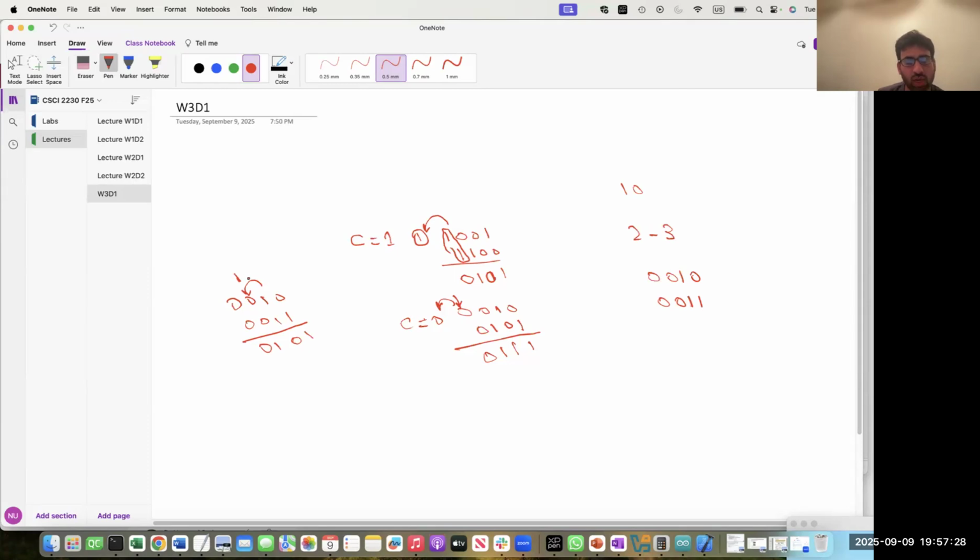So when I have a carry from the half position, or half the size of the register, then your H flag will be set equal to 1. I'm just giving the example using 4-bit, but actually we have 8-bit, which basically means that when there is a carry out from bit position B3 to B4, then your half carry flag will be set equal to 1. But if there is no carry out from bit position 3 into bit position 4, then the H flag will be set equal to 0.